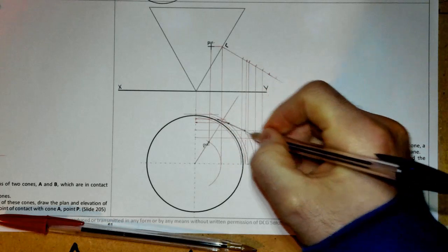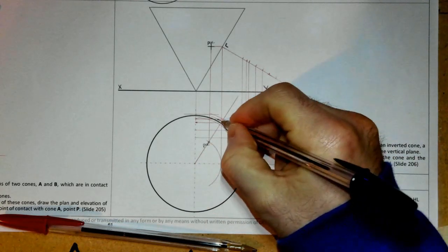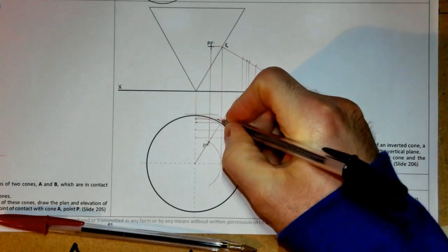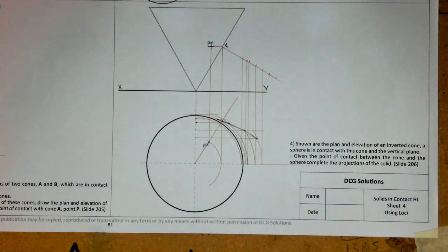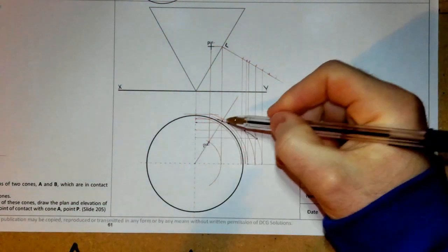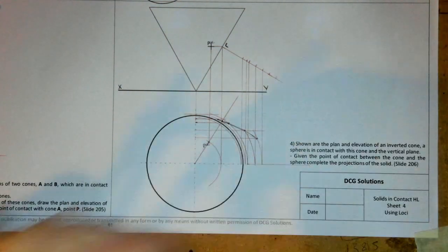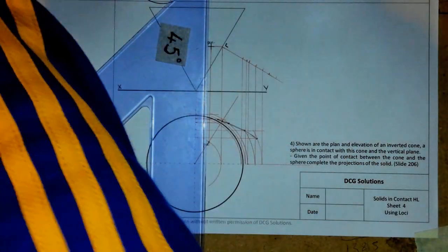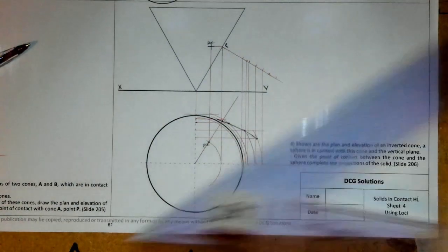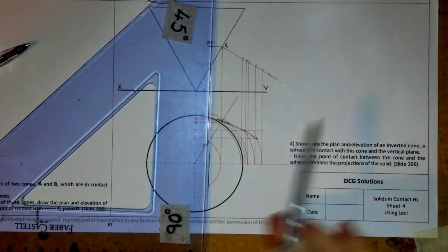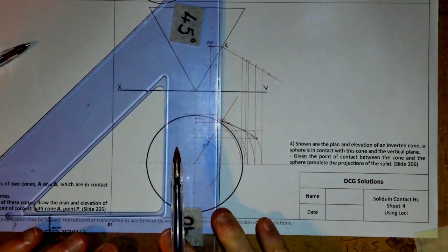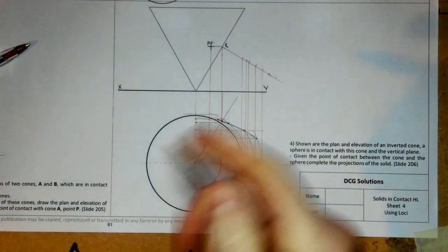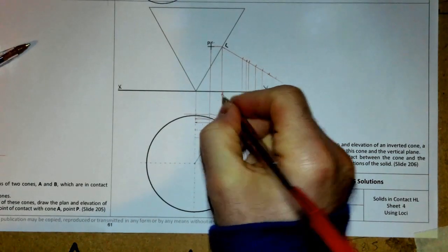Okay, so now where that crosses over, remember our center was out along here, that point right there is our center. And you have to remember it touches the vertical plane, so the distance, my radius then, is from here up to the XY line. So I'm going to pop that in there. I'm going to put in a straight line up to it. So there's a bit in this one now, guys, just understanding. That was a little bit tricky. So that distance there that I've just put in, that distance from there to there